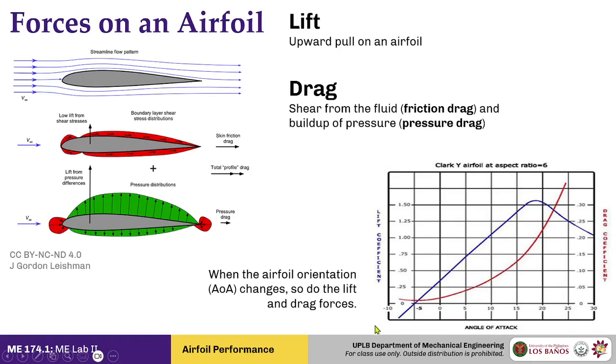Now, what you notice here is that as the airfoil angles upward, the lift increases, but only up to a certain point. And it starts to decrease after you exceed that particular angle. Well, for the drag, it starts out small, but it just grows and grows as you increase the angle of attack.